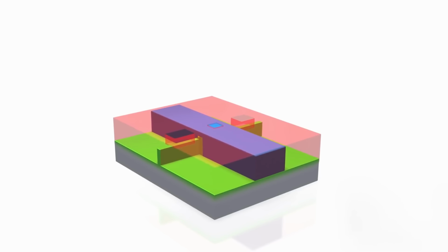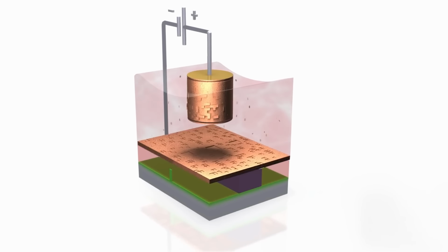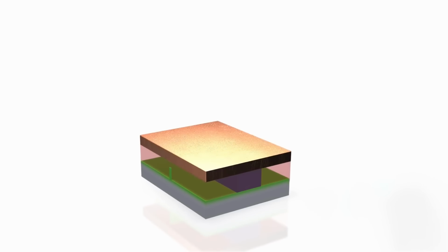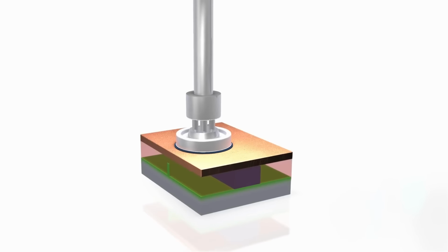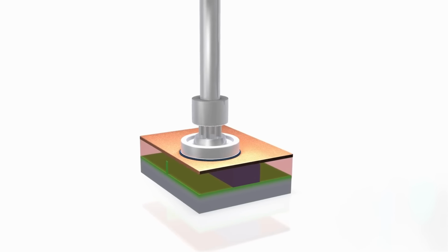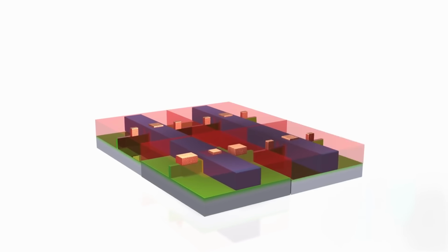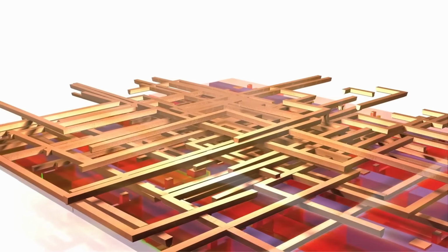Manufacturing the metal layer is already a very complex production step, as you have to connect billions of individual transistors to super small wires. If the cells placed in a row would have different cell heights, planning and placing the metal layer would be even more complex. It's not impossible, but because of automation and workflow optimizations, cells inside the same row and the same logic block usually use the same cell height.